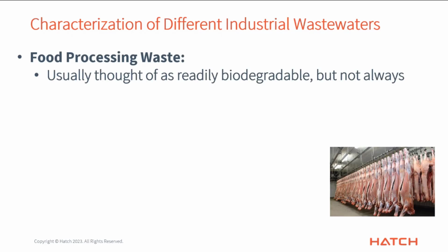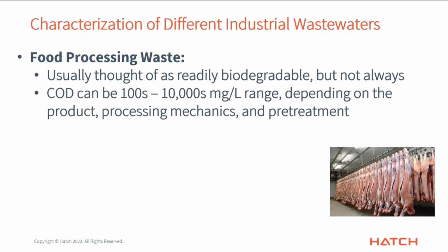So food processing waste, by that I mean wastewater that comes from a factory that makes some sort of food product, is usually thought of as being readily biodegradable, but to be honest, my experience has been surprising. It's not always the case. We had a project about 6 years ago with a regular municipal plant here in Canada. They received waste coming from a pasta making facility, and I was really surprised how not biodegradable the wastewater from the pasta place was. It was not completely inert, but it was not as super readily biodegradable as I maybe would have expected.